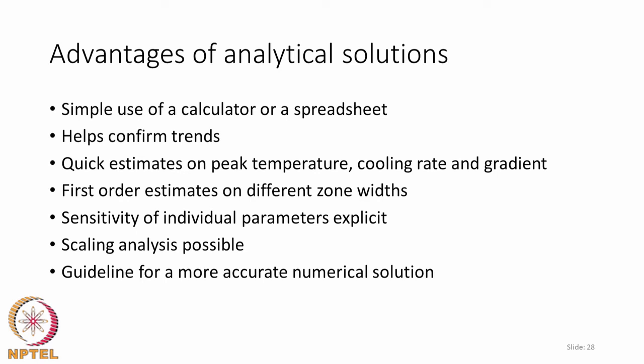And very often we want to confirm the trend of the numerical solution or the analytical solution as we change a particular parameter. We could do that quite easily now because the analytical form is available, and by differentiating with respect to the variable we want to change, we can confirm the trend of the temperature profile variation. We can also use these expressions to quickly estimate the peak temperature, cooling rate, gradient, etc.